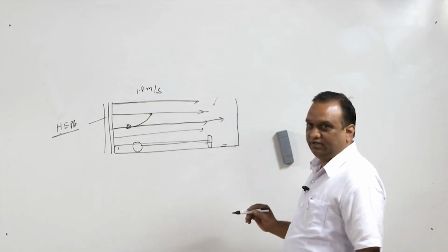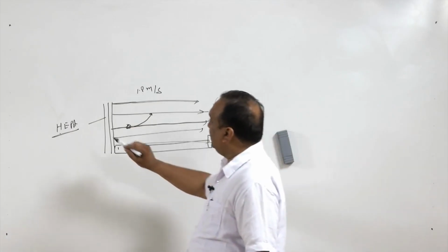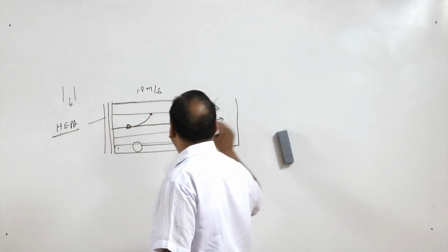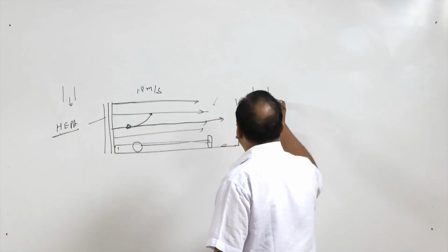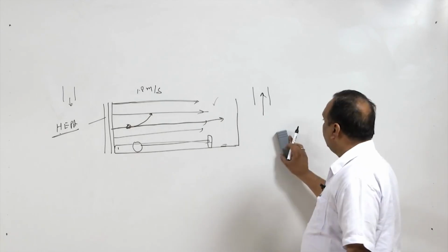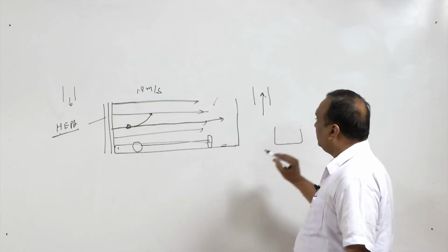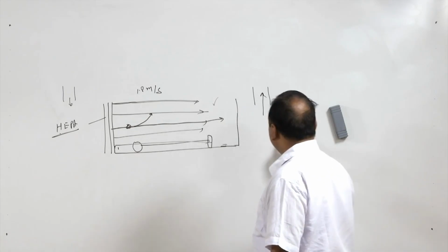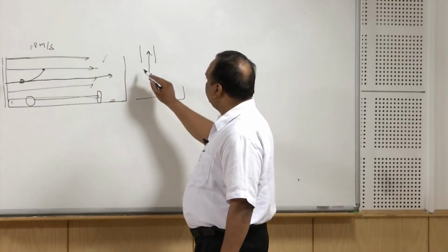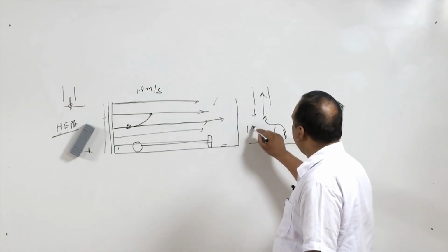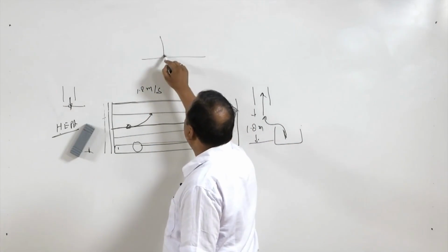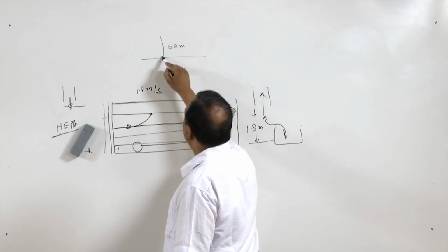In addition to this, the exhaust and inlet in the hospital have to be taken care of: the exhaust of air to the atmosphere and the inlet of air for air conditioning purposes. There should not be any waste disposal site close to the inlet, because this may contaminate the air. For this reason, it is always recommended that the inlet should be approximately 1.8 meters over the ground level, and if the inlet is at the rooftop, it should be approximately 0.59 meters above the roof level.